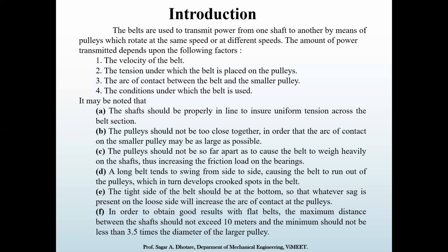So the tension between these two pulleys is difficult to maintain, and because of that improper tension, swinging or movement of the belt can occur, and because of that, it could run out, or you can say away from the pulley.